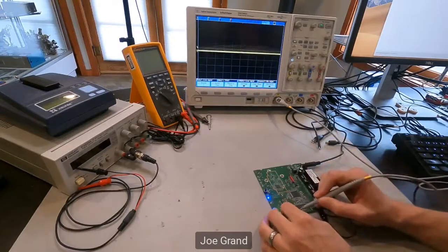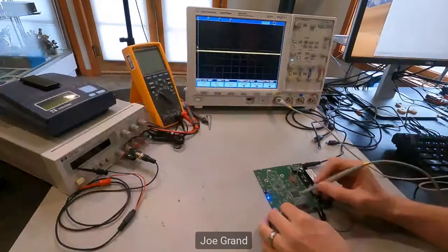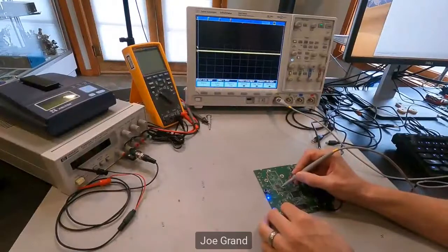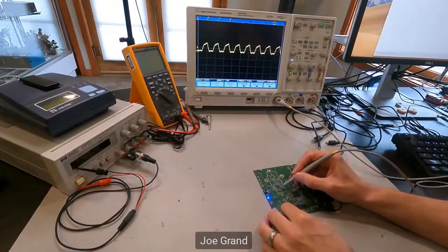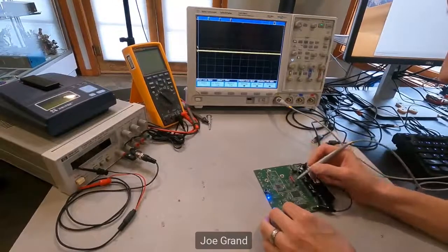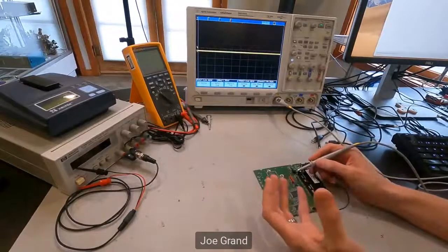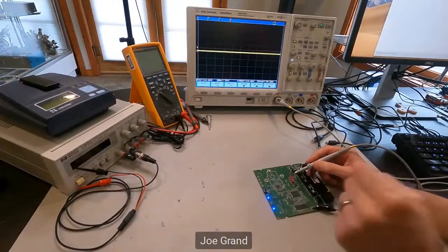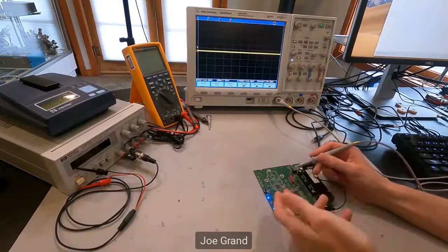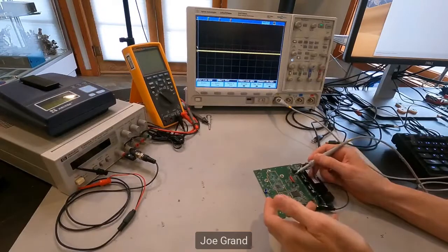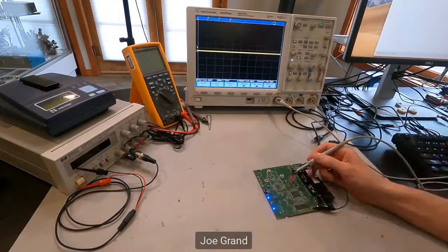And I'm just scraping my probe around. I think over here, this is like the wireless chip. Oh, there's another. Okay, so another 40 megahertz signal for the wireless chip. Now, one thing to keep in mind is a lot of times the things that we're interested in, and in this case, what I want to look for is some sort of boot log information, because that's going to bring us to our next demo.